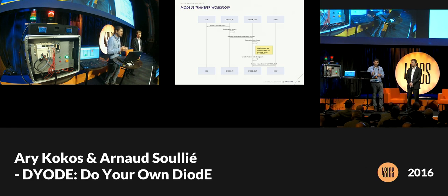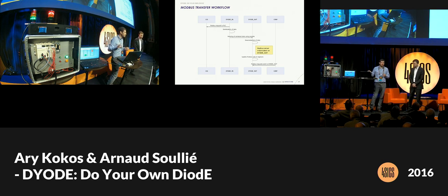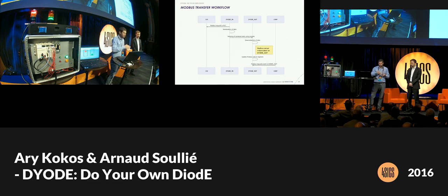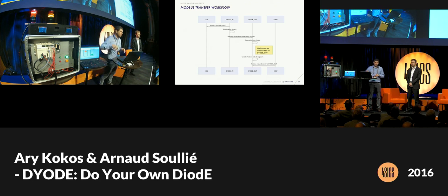Those values will be serialized, sent over a UDP connection to the output Raspberry of the diode, and on the output Raspberry, we have a Modbus server that will update its value with the one sent by the input counterpart of the diode. So from the corporate network, I'm actually sending requests to the Raspberry Pi that will act like a PLC. So that's the easiest solution that we find.